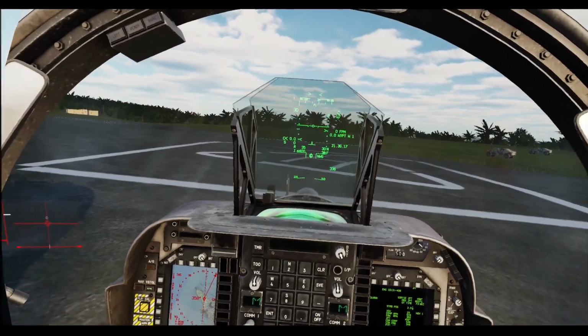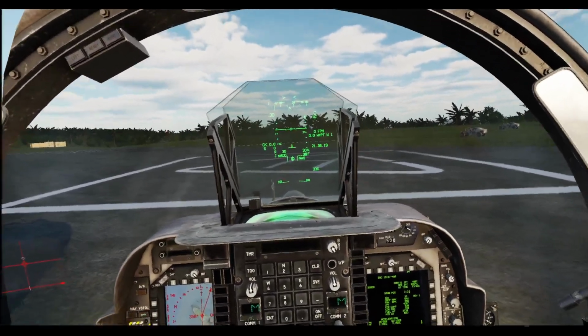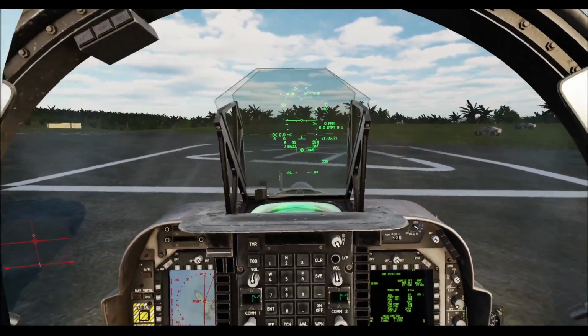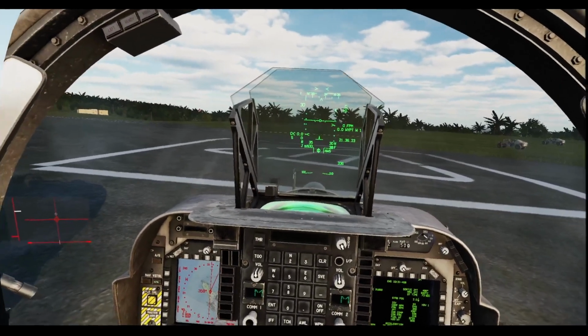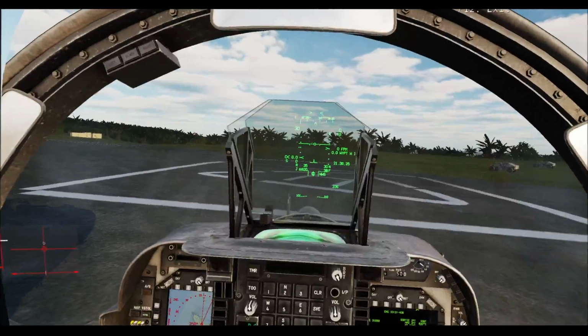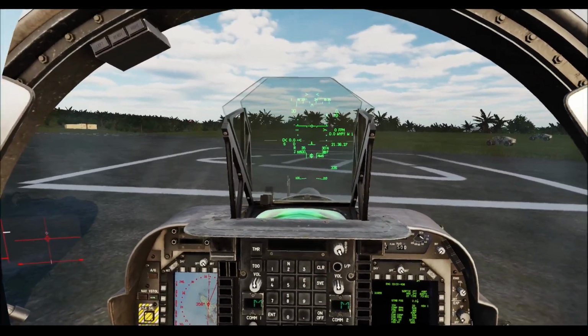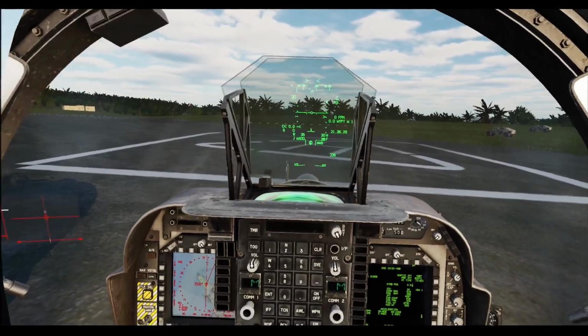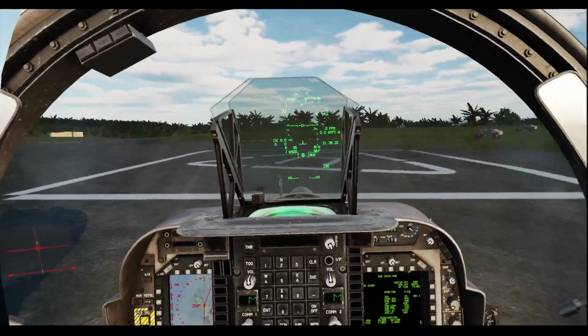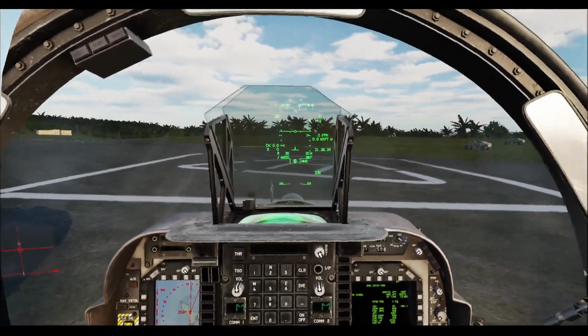During the turn, I'm going to gate myself. I want to be between 500 and 600 feet on the 90. Once I reach the 90, I'm going to bring the nozzles back to 77 degrees. I'm then going to next look to be at the key at 325 feet at 0.6 miles, and then I will perform the rolling vertical landing.